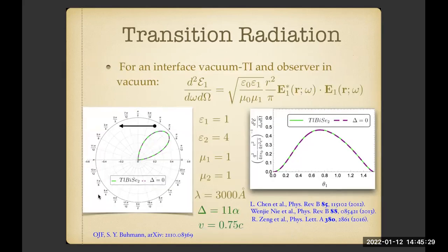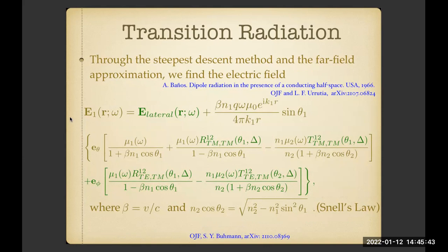So as I told you, everything in this framework is a right-handed triad between the electric field, the magnetic field, and the wave propagator. And that could be seen here if you take the scalar dot product between this electric field and the direction of the wave propagation, which is parallel to the radial direction, everything goes to 0 once one rules out the lateral waves, which are not important for the radiation that we are going to study.